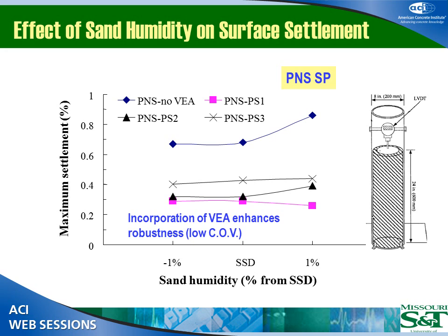More surface settlement, that means more internal bleeding, maybe external if you can measure it quick enough, and also more segregation. If I change my superplasticizer, or I add viscosity agents, you could see over here, everything is much more stable. So the surface settlement is lower. We like a maximum limit over here of 5.5%, so everything is lower, and there's very little variation also from going to the high water cement ratio from the SSD.